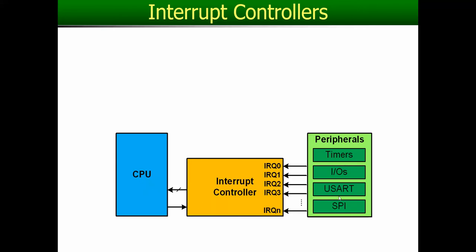So the USART will interrupt the CPU when the entire byte has arrived in the buffer register. The same is true for transmitting. When transmitting a byte, the CPU needs to be interrupted every time the previous byte has been sent completely. Only then can it give another byte to send. We'll see serial communication in a separate chapter on that.